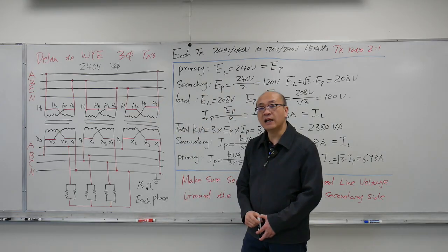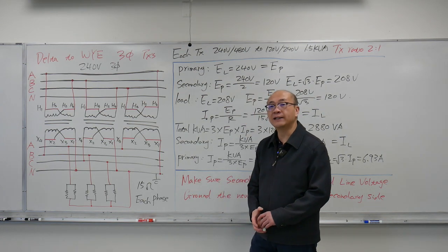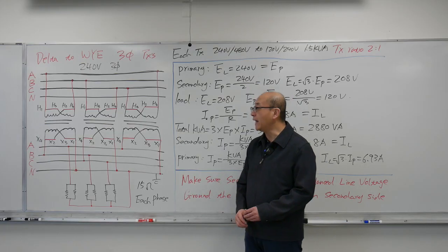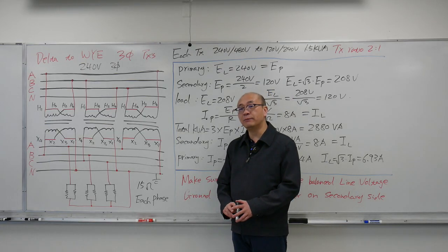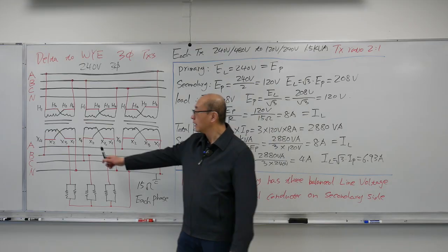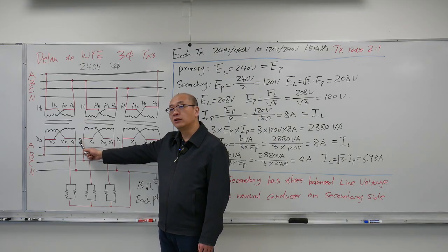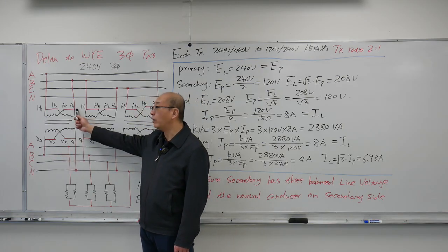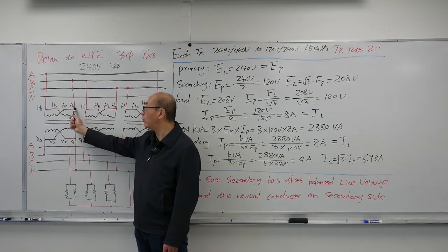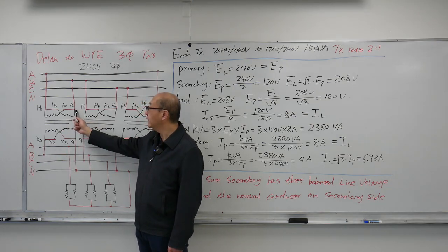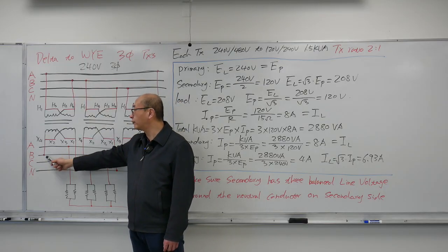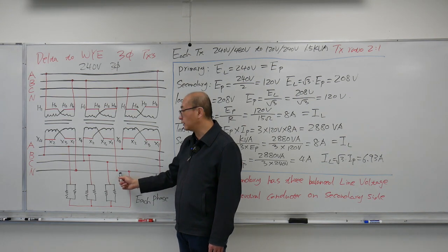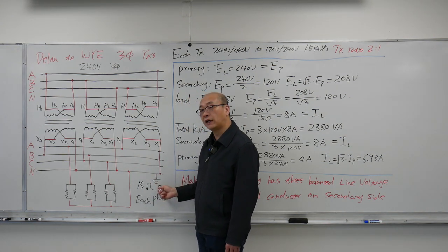The secondary is the most important one, because the CSA requirement is that the phase displacement is 30 degrees. So the connection for the secondary is very important to know, because if you remember the phasor diagram, or the summary I gave you, the H4 has to follow wherever X4 is, and H4 and X4 connect onto the same line. So here, H4 connects on line B, and X4 we also connect onto line B. All the transformers' X1 connect onto the neutral, and I ground the neutral down here.